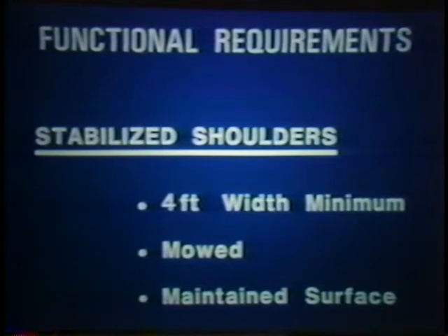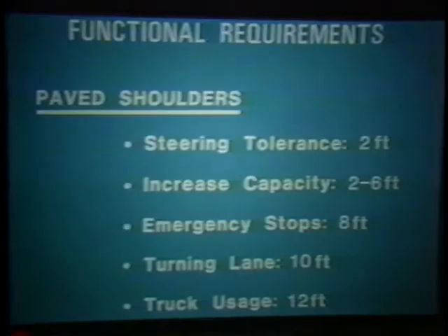Ruts, depressions, and pavement to shoulder drop-offs should be graded out or backfilled. Paved shoulders, even those only 2 feet wide, will increase the effective lane width by greatly reducing the drop-off and loss of steering control problem.